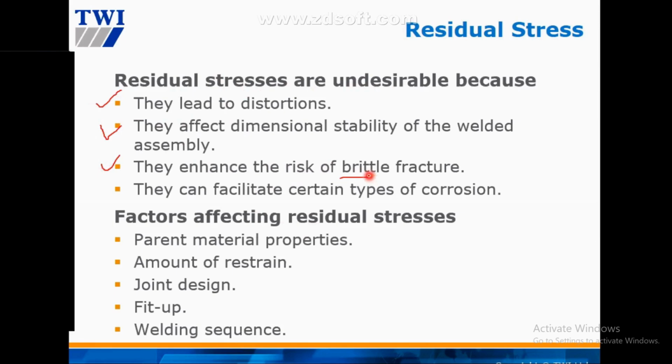Residual stress can facilitate certain types of corrosion. Factors: parameters and restraint. Restraint, we understand, is material not free to move, joint design, fit-up, and also welding sequence.